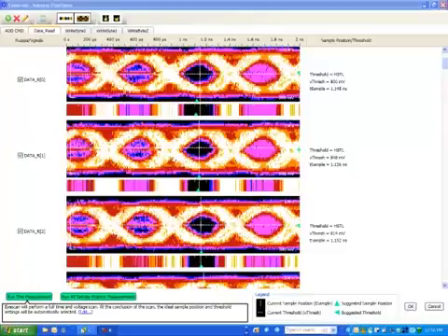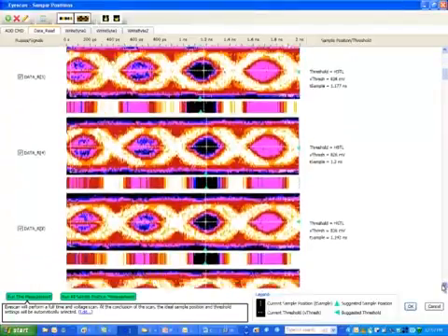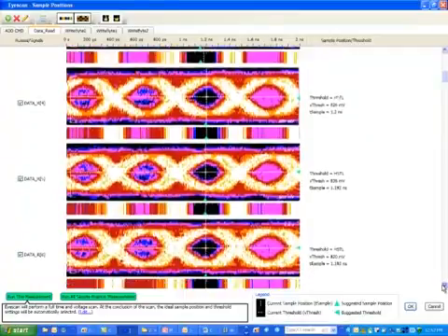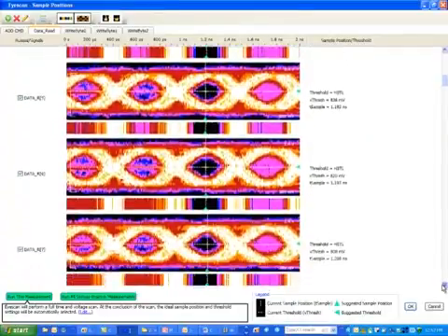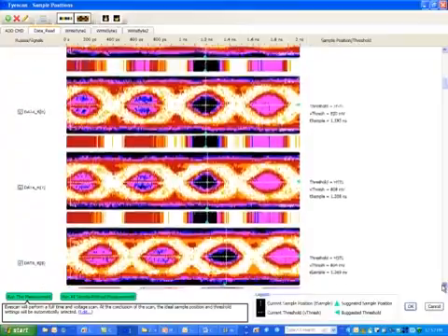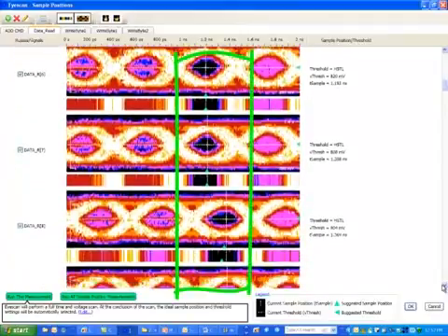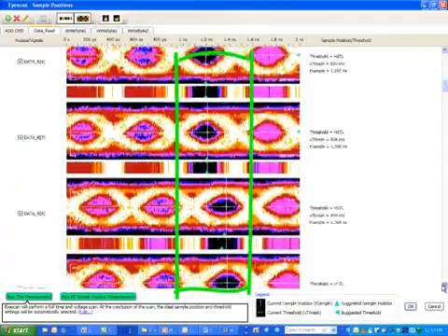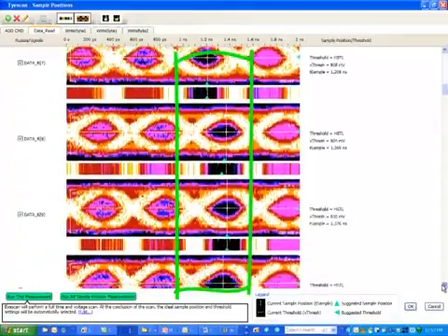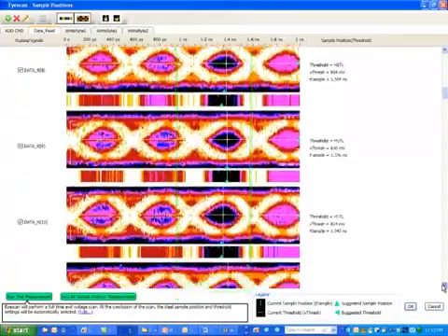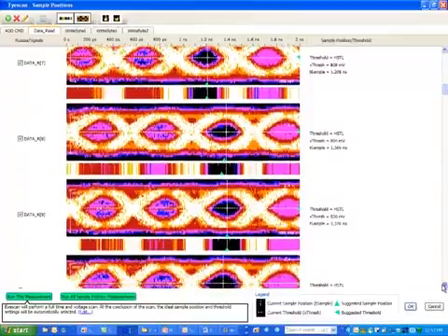Scrolling through the data, we can observe the signals relative to each other for quick signal integrity insight. We get all of the signals in the system. Here between bit 7 and 8, we see a byte lane shift, which is expected. Note that almost all of the eyes are relatively the same size. That is, at least for the first 2 byte lanes.